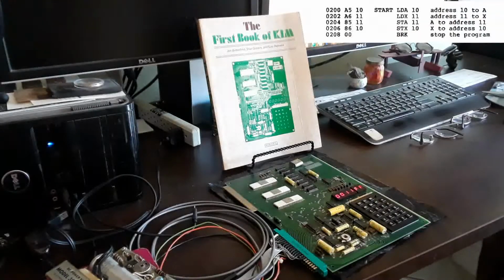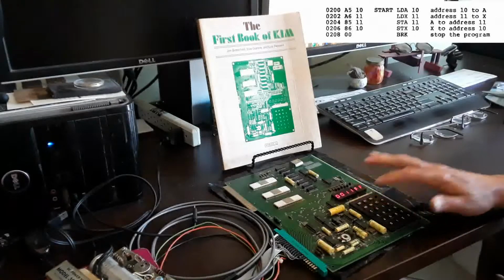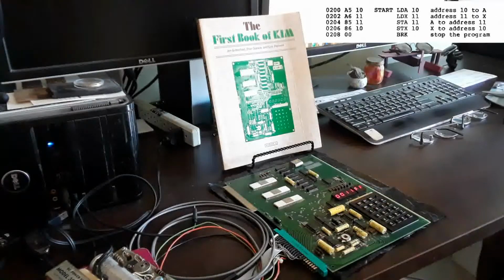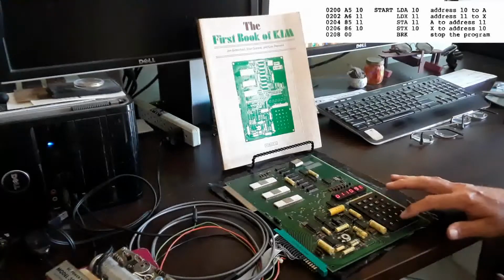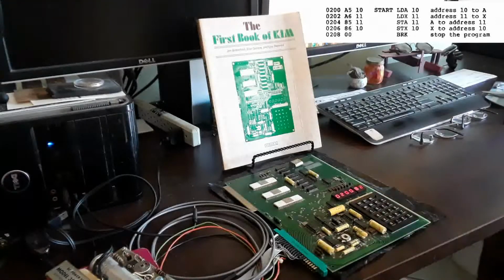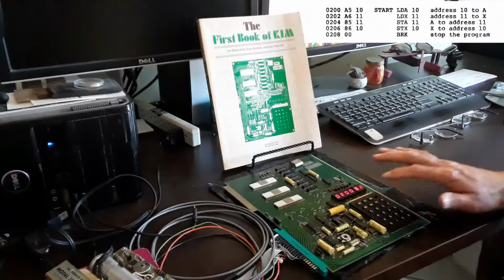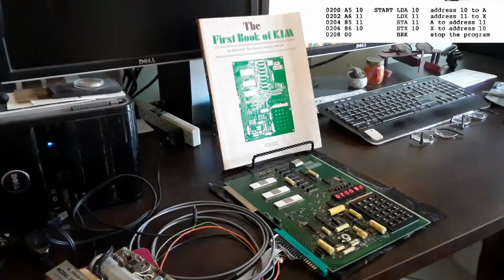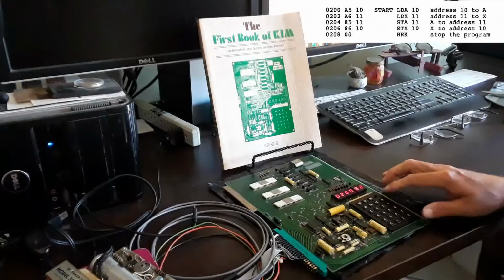Now we are ready to load our program. So let's start by going back into address mode by pressing AD and entering the starting address of our program, which will be 0200. Now let's go back into data mode and enter our program one step at a time. First, we will enter A5,